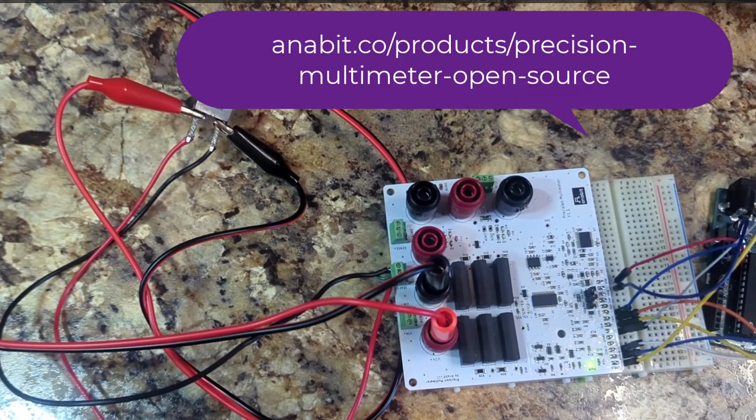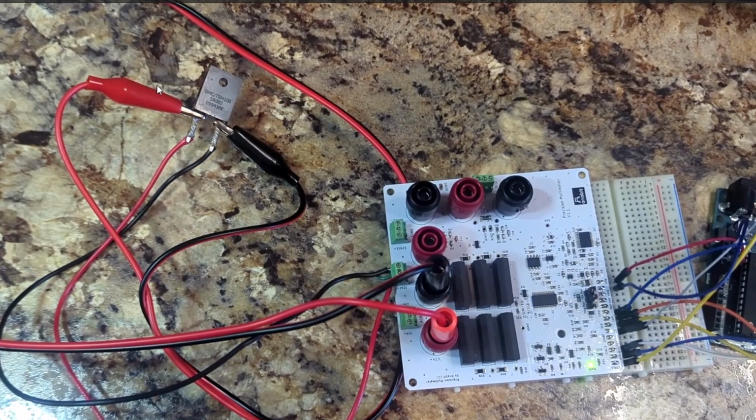Okay, so here we're looking at Anabit's precision multimeter open source design right here. We're looking at it from its side, and we're using an OG Arduino board, the Arduino Uno. This is the resistance we're measuring. So I chose a low resistance to kind of show one of the benefits of this method. So this resistance is about 5 ohms right here. And you can see we're using a 4-wire method.